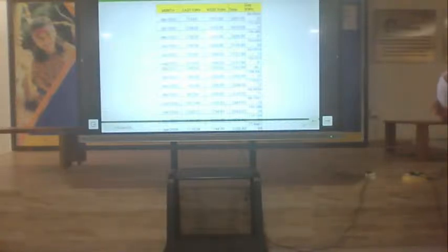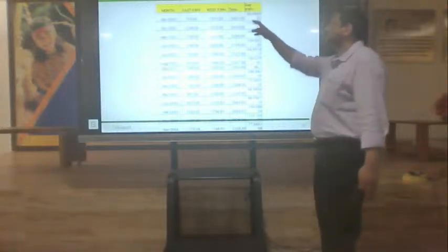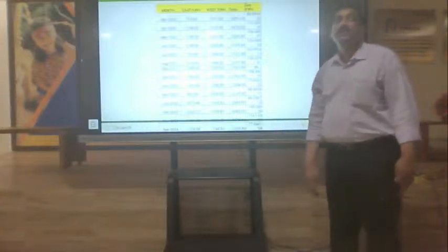Suppose if I reduce my current regulation from 10 amps to 9 amps, automatically the terminal voltage will increase. So what is that value by which I need to reduce my current? Each time, the current limit of the circuit is being changed, so that all the energy generated by the solar is being pumped into the load. That is what your MPPT is. So this is the usage of your DC-DC converters.